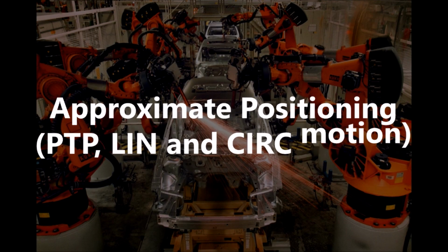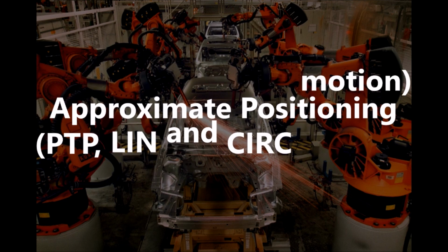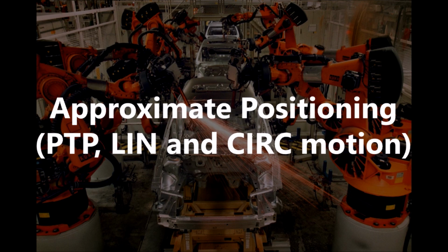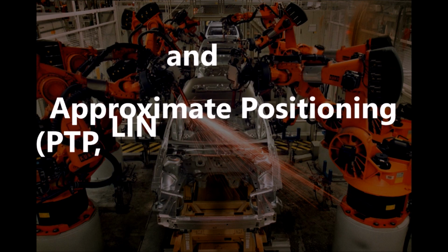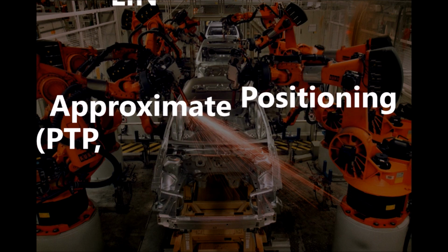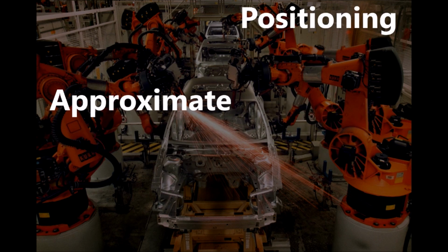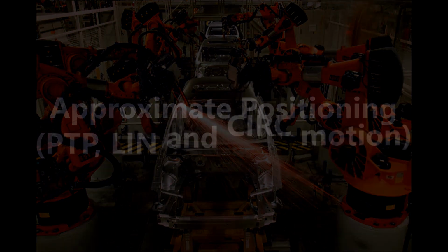Now, let us talk about the approximate positioning function. Approximate positioning actually means that the motion does not stop exactly at the programmed point. Approximate positioning is an option that can be selected during the motion programming, for example, PTP motion, linear motion, and circular motion.